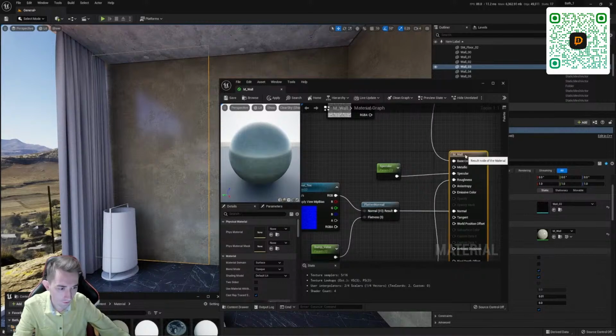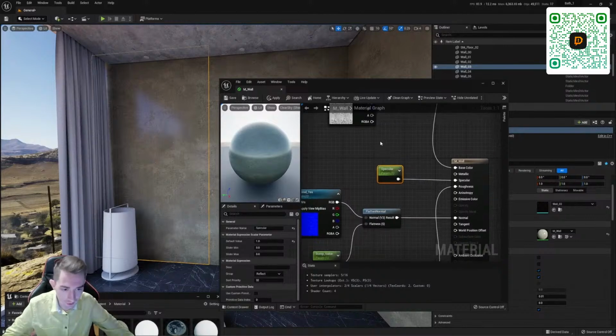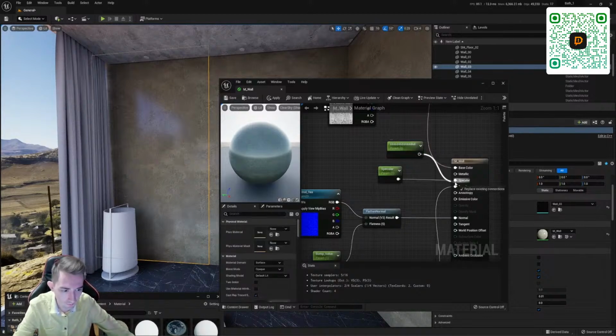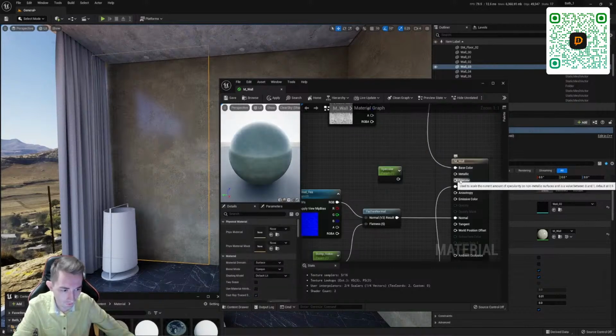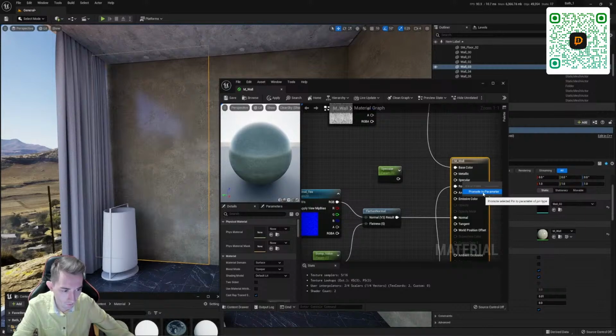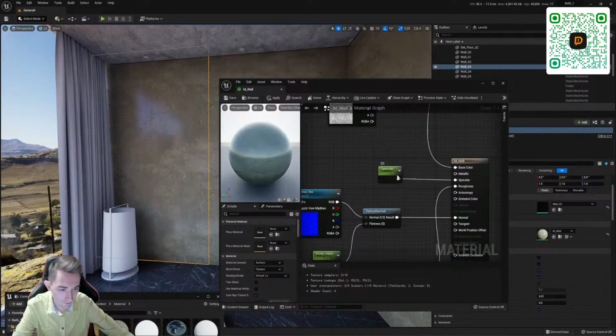Specular is a type of reflection for us, as in 3D Max, when we create materials, reflect is Specular. I'm creating a parameter. You can create a parameter with C. Hold down C on the keyboard, press the left mouse button. We create a parameter, and we call it as we like, and connect it to the channel, for example, specular. Or you can make it easier. Right-click on the specular and click promote to parameter. That is, to fall into the parameter. It will create a node like this, and we have control over the reflection.